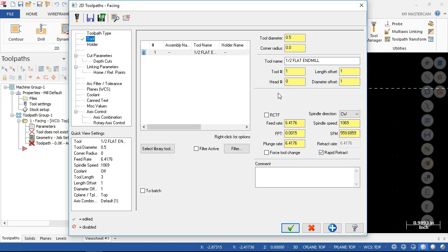All right, so feeds and speeds into the aluminum. If we go with the surface feet per minute, let's just try 800 surface feet per minute. That gives me 6112. All right, that's kind of a weird number. I may have a spindle that runs 6,000 RPM, 7,500 RPM. Well, okay, let's start at the lower end. I may have a spindle that runs 4,000 RPM, 6,000, 7,500, 10,000, 12,000, 15,000, 30,000.